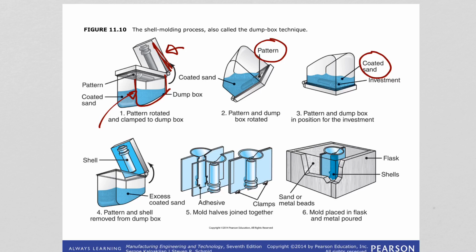In this case, the shells are very light and thin, as you can see, and the thickness of it can be determined by controlling the time the patterns are in contact with the mold. So of course their thermal characteristics will be different than those for the thicker molds.